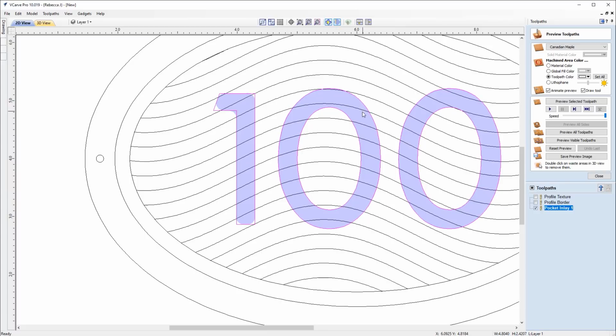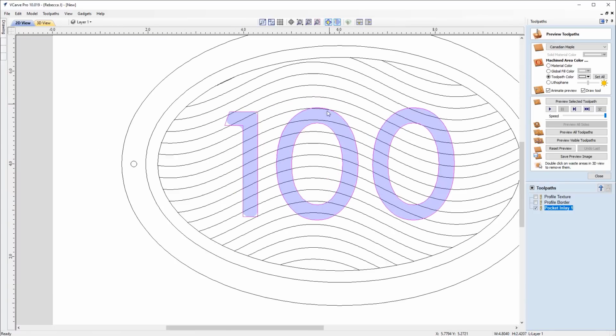Okay, so what the inlay toolpath does is it takes our vectors and the tool, so the radius of the tool, the diameter of the tool, and it creates the pocket for us. And the reason why we're using the inlay tool as opposed to the pocket toolpath is because when we come to create the male counterparts, the actual cutout numbers, it's going to create the same pattern.